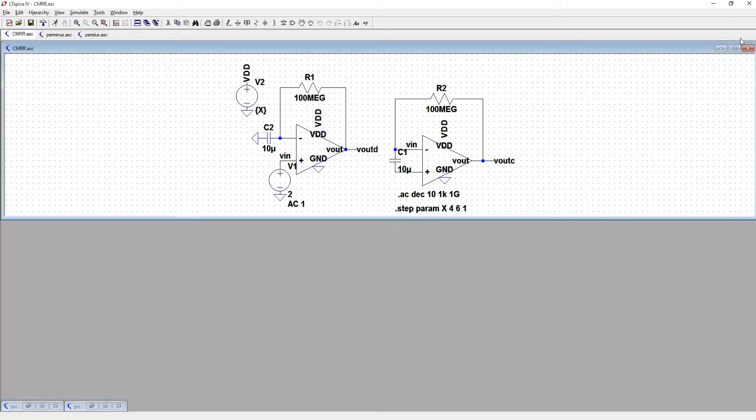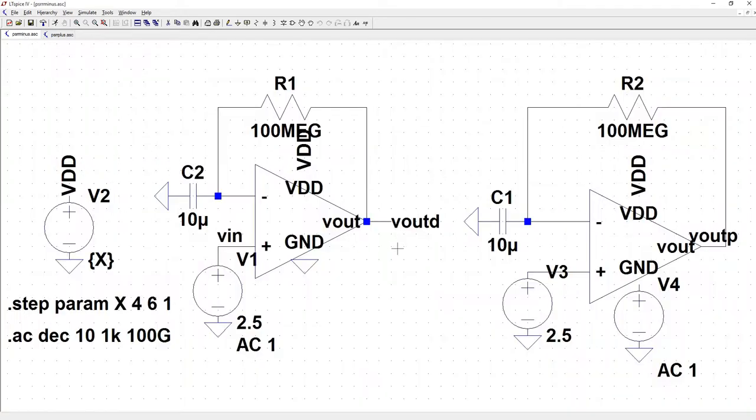So let's get rid of this. Okay, so now when we're talking about power supply rejection ratio, you have to look at both the plus and the minus. And this is very similar. We're going to be looking at a ratio of output, so it's the exact same circuit, one set up similar to how you would if you just had a basic follower feedback configuration with no gain. You're biasing it at 1/2 VDD, and you actually want both the V plus terminals of both sets of circuits to be the same.